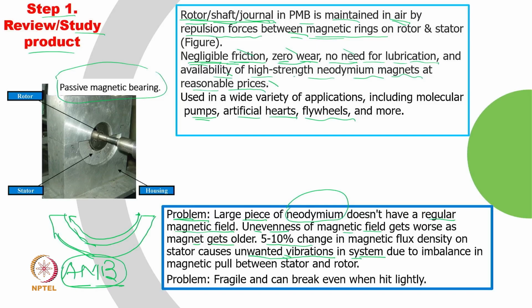It will cause a vibration problem, and then if the rotor really strikes against the stator, and permanent magnets being very fragile, it can break the permanent magnets also. Once the permanent magnets are broken, then complete failure occurs. So, these are the major issues.